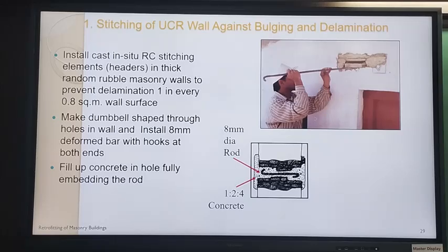With that we would start removing the mortar from all around. Once that is clean, you start prying it, a little bit this way, that way. Slowly the stone becomes loose, you remove it. And you make sure that you always leave some stones here or there. If you start pulling all that out, then the hole gets bigger.